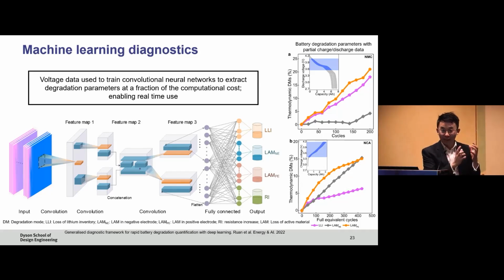So what we've been doing is augmenting the charging current based on the loss of active material in the 2 electrodes, because if you've lost 20% of your graphite and you're still charging at the same current, you're effectively increasing the C rate on the remaining active material. So hopefully that acknowledges that there is uncertainty in the system, which I think was your original question, but also ways forward, maybe using Bayesian statistical methods to understand how we can take new measurements and increase the accuracy of future predictions.